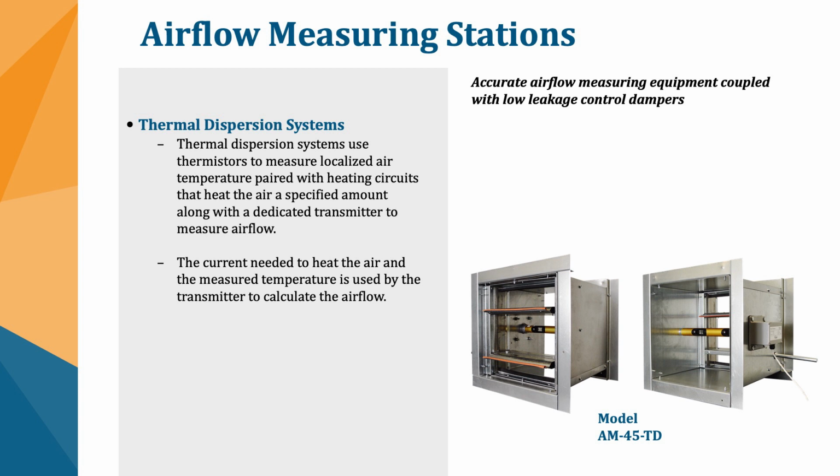So these thermal dispersion units that we have available now, we really only have available with a damper. We don't have a standalone unit for that. And that thermistor is heating that air locally and calculating that airflow, similar to the way the pressure differential transmitter is calculating the airflow through some type of pressure transducer.